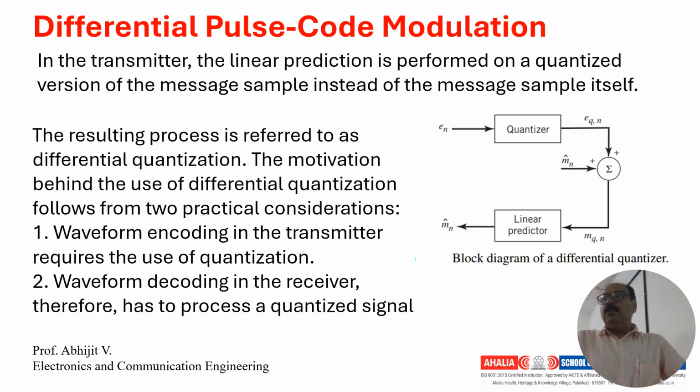This is the block diagram of a DPCM. Here in DPCM, instead of taking the message sample itself, we are using a linear prediction to the quantized output.